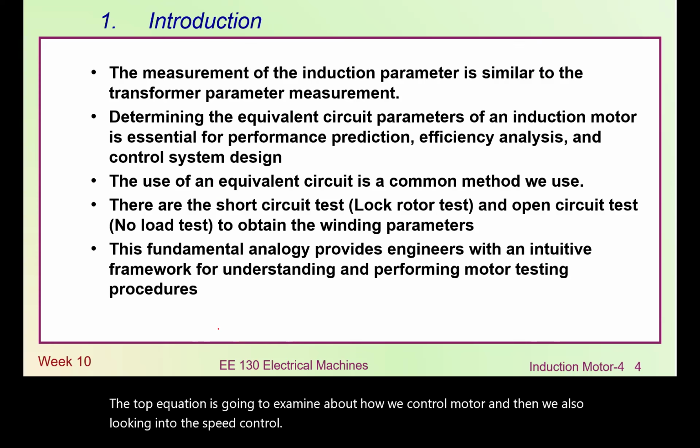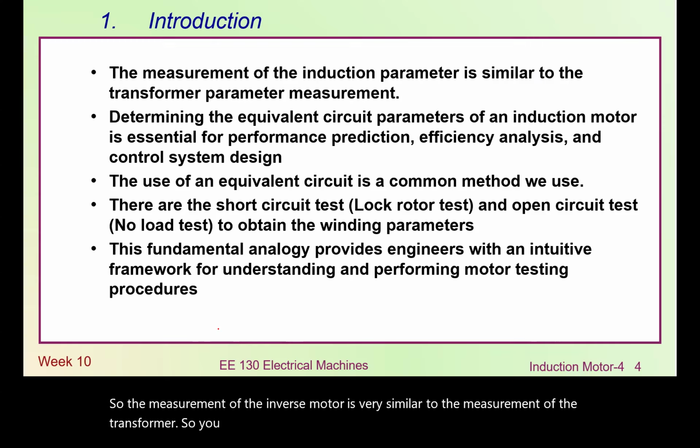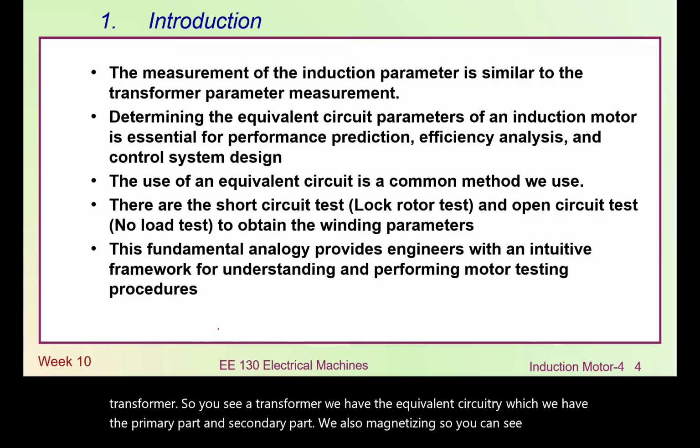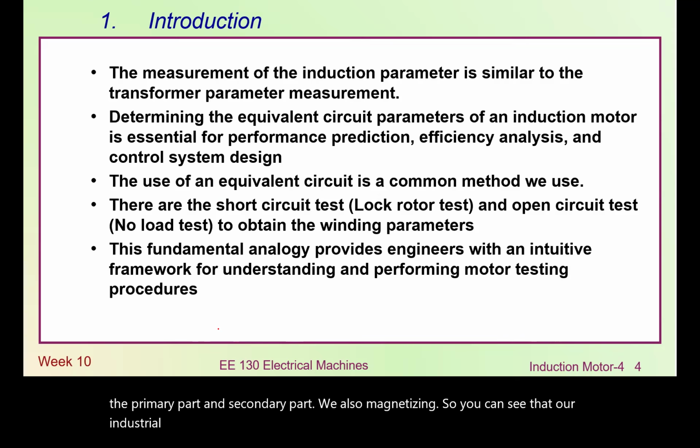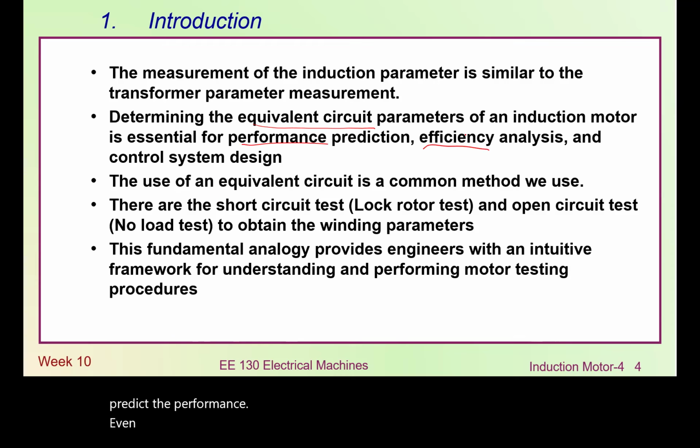The measurement of the induction motor is very similar to the measurement of the transformer. In a transformer, we have the equivalent circuitry, with the primary part and secondary part. We also have magnetizing. So you can see that our induction motor equivalent circuitry is also quite similar. Here, we can use the equivalent circuitry, which we can convert into a torque equation. We are able to predict the performance, even the efficiency. More importantly, will be how we control that.